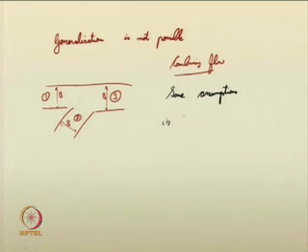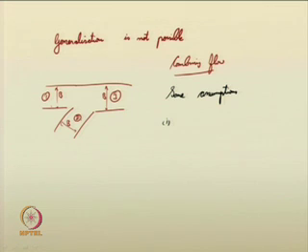You can just note it down: flow occurs from channel 1 and channel 2 and merges in this junction and goes through channel 3. This means there is no reverse flow occurring there. We also suggest that the flow is parallel to the channel walls. So, it is parallel flow occurring in all the channels, that means there is no turbulent 2-dimensional flow mixing and all. This is predominantly 1-dimensional for each of these channels based on their channel axis.